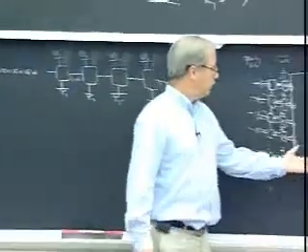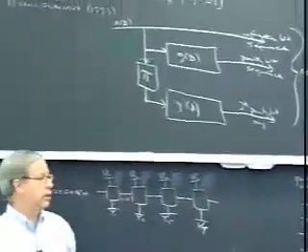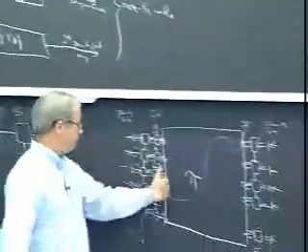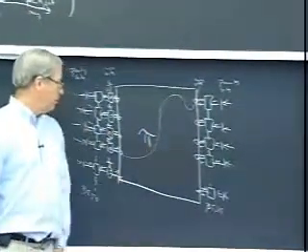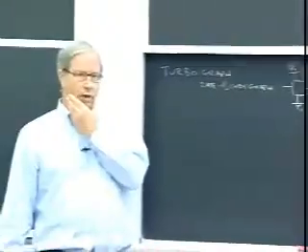This is called parallel concatenation, where you have these 2 codes in parallel and just pass information bits back and forth between them. It's typical that you get poor minimum distance, which eventually shows up as an error floor.